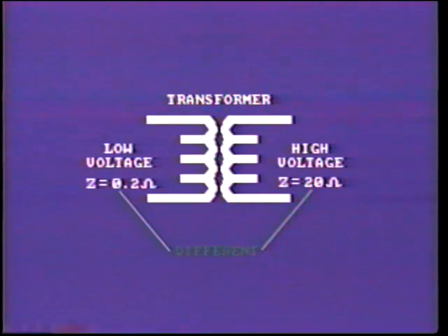In fact, the impedance of a transformer appears to be different when viewed from either the high voltage or low voltage side. The ohmic impedance is lower when measured from the low voltage side. The method applied to get around this problem is to express all values as a percentage of a common base. This is known as the per unit system. Now, aren't you glad that you reviewed this subject in videotape number 3? Let's briefly review it once again.